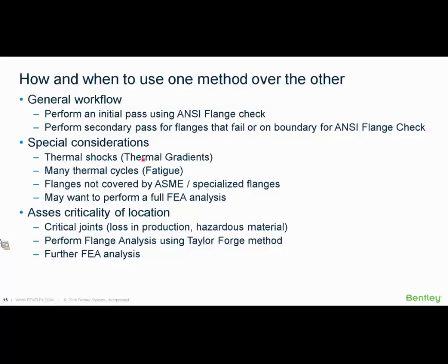And then if fatigue is a concern, that's another area in which you can look towards having some special consideration, or maybe go for a full FEA analysis. And for flanges that are not covered by ASME, or if there are some specialized flanges, that is also a scenario in which you could think about going for a full FEA analysis instead of using the Taylor force or the equivalent pressure method that are available.